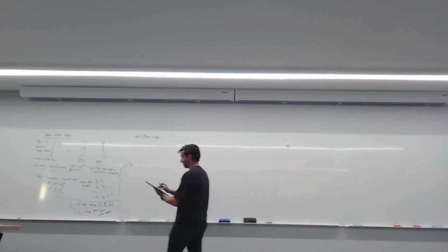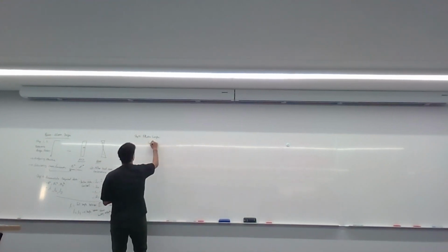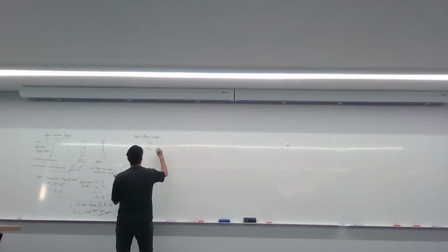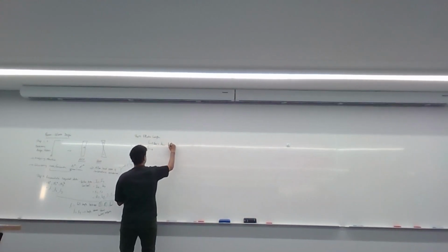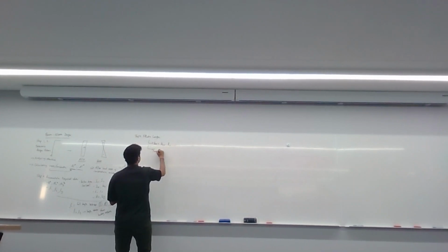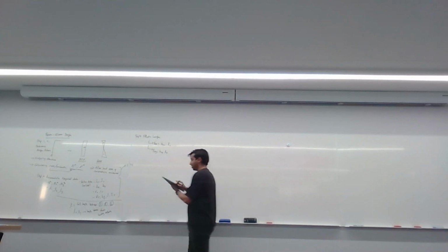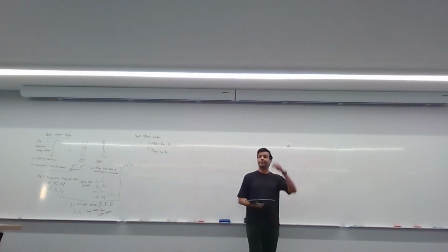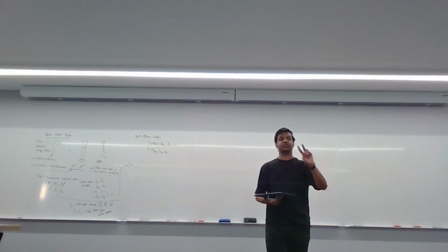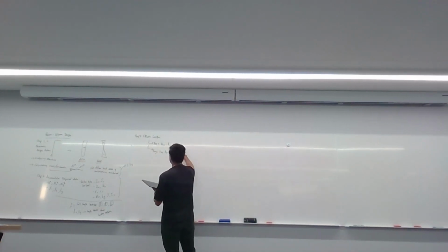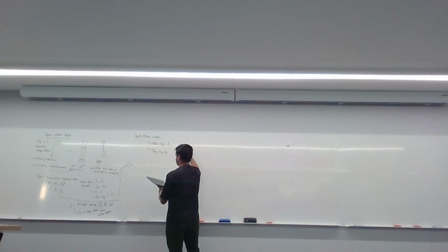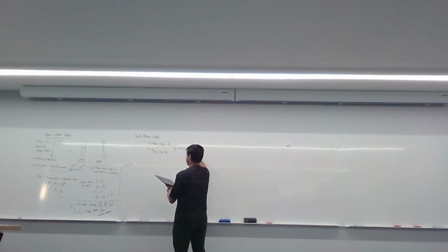But anyway, let's have a look at the effective length. For effective length, we need them both in the x and the y direction. Lex is equal to Kex times Lx. Ley is equal to Key times Ly. Okay? Now, where do you get your effective length? Remember, in the course, there were 2 versions of this that were covered. The first version is a simple one. By the way, this is from clause 4.6.3.2 or 4.6.3.3. Okay?